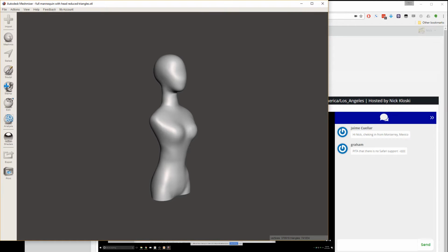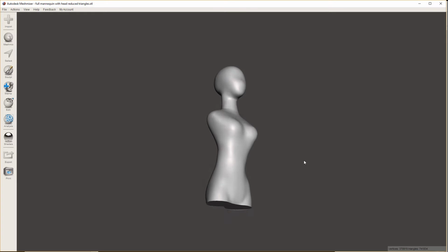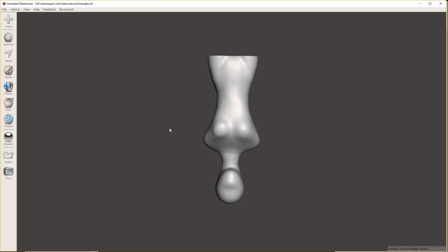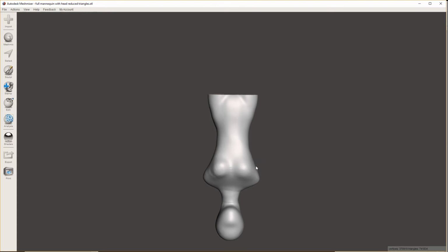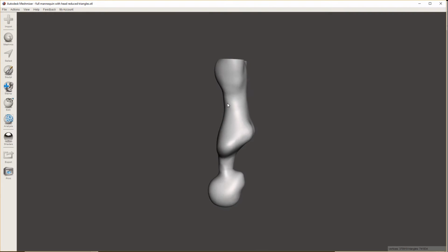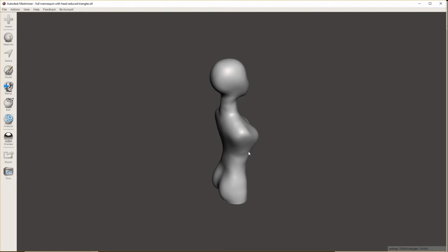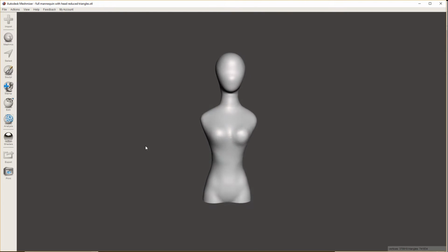So I guess Cynthia works with figurines, and she had a question about how to do hollowing. Since she is printing on a new resin printer, the printing process is different. These objects typically get brought out upside down; essentially, they're pulled out of the build plate from the bottom. So the figurine would print out like this. Now, for hollowing, Cynthia, I would ask you to ask questions on the webcast if I'm not going over this, but I did some hollowing on this, and it worked pretty well.